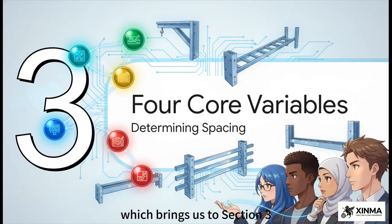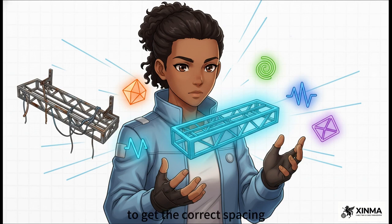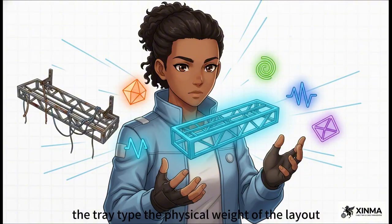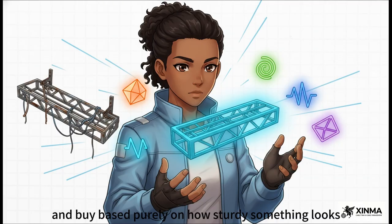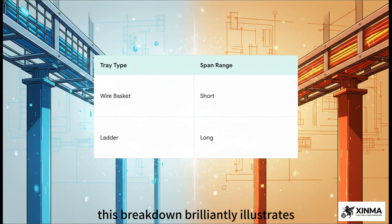Which brings us to Section 3, the 4 core variables determining spacing. True structural integrity really requires a holistic engineering framework. To get the correct spacing, you have to look way beyond just checking a tray's thickness. You need to simultaneously evaluate 4 things: the tray type, the physical weight of the layout, the specific environmental load, and the overall structural geometry. If you ignore this multivariable reality and buy based purely on how sturdy something looks, you are practically guaranteeing a structural failure.